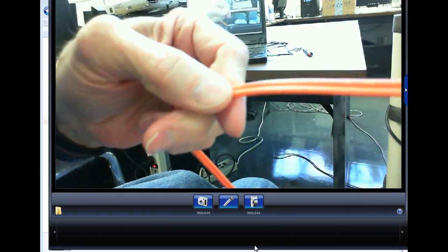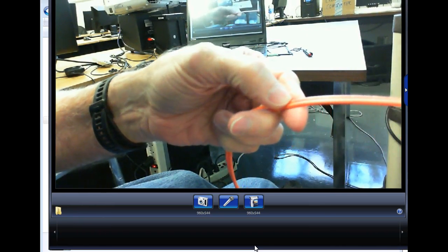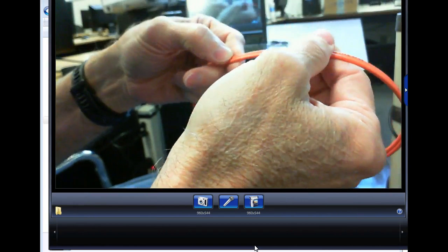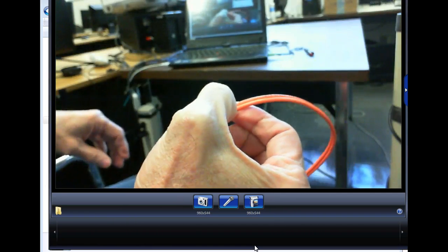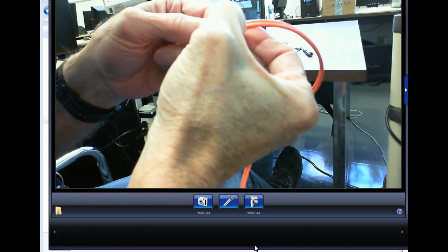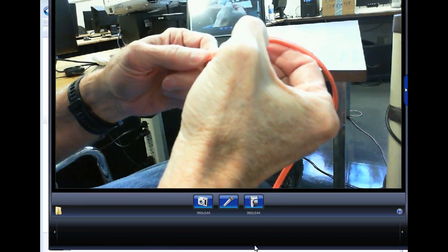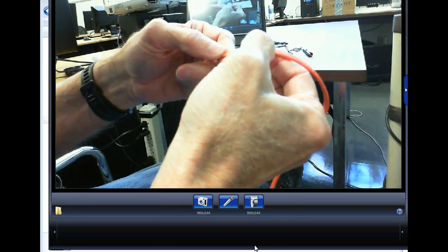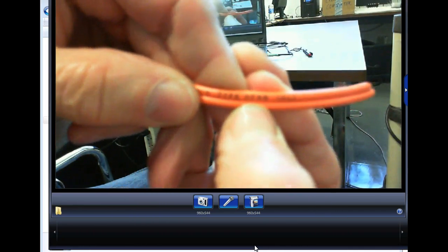This was put out by a company called Chromatic Technologies Incorporated, 50/125. So what is the 50? What would y'all think? Sort of, but we don't say wire gauge, right? So 50 is the size of the core. 125 is the size of the what? The cladding. That makes sense. This outside jacket is OFNR.